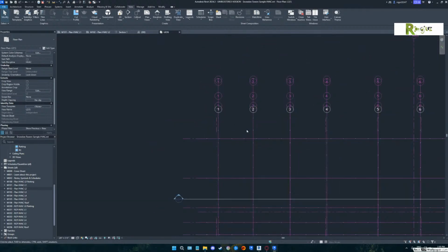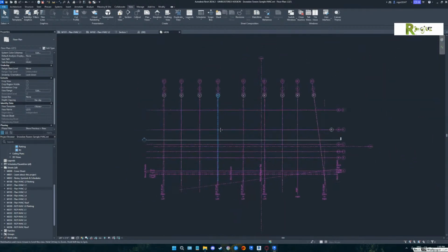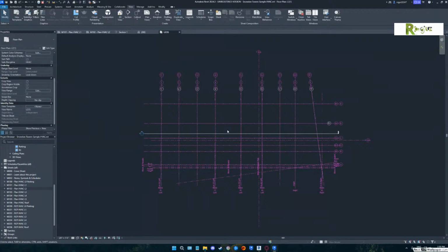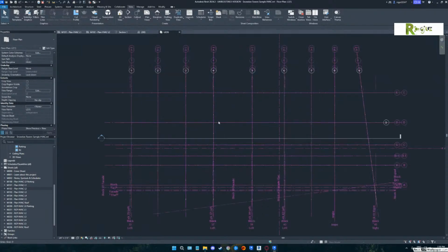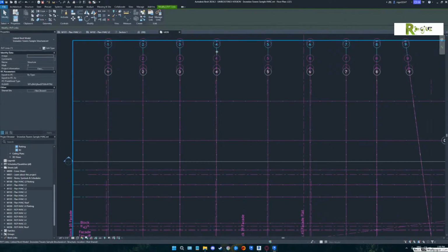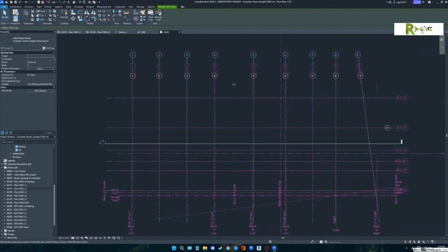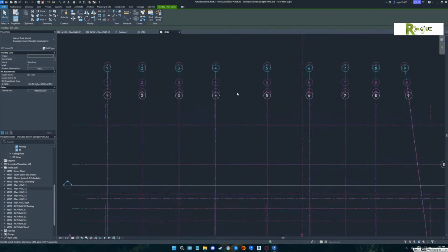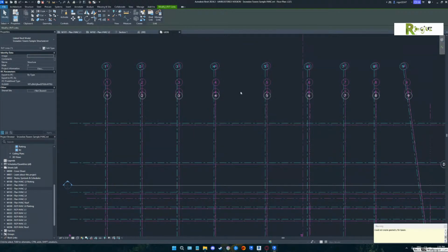You see how you can have this view only have your grid lines on. So every now and then you go into the sheet to make sure that one of your objects didn't move. If you picked one of the purple grid lines, just one of the purple Revit links, yep, that was perfect. Use your nudge arrow 2 times to the left and 2 times up. You see how you can tell which one's off? Yeah. Right?